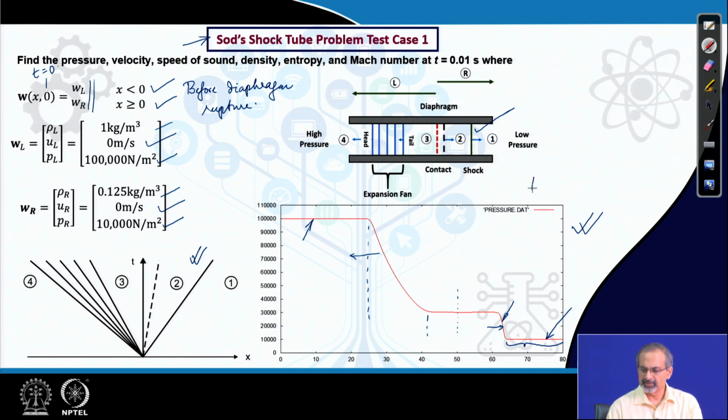So, the one dimensional Euler equation has been solved using an appropriate numerical scheme, which uses the conservative form of the equations and appropriate discretizations to account for the characteristics, and then finally comes up with this distribution of pressure. So, we are just looking at the final solution.